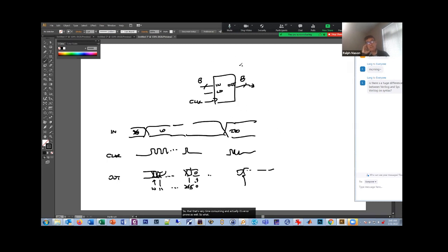So what we really want is something that says, okay, let's say we get a random number of clocks. We're going to load random values in, and we're going to have some expected counts. We're going to write a program that says after this many clocks and this random loading, I expect this count, and I'm going to do all that automatically.